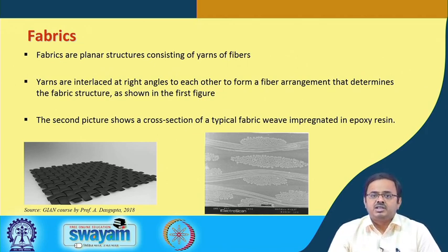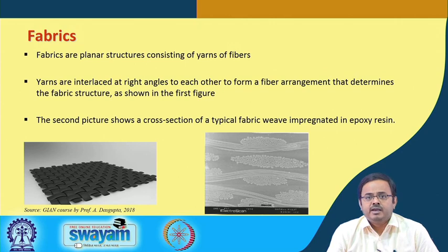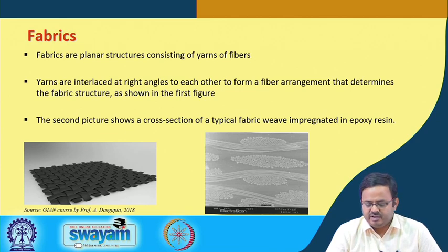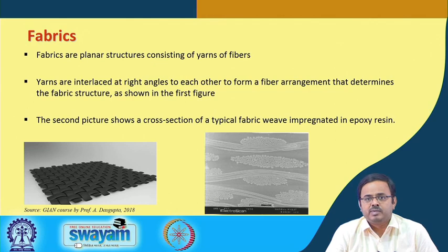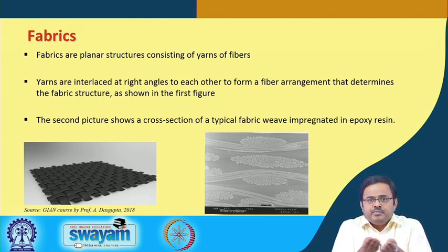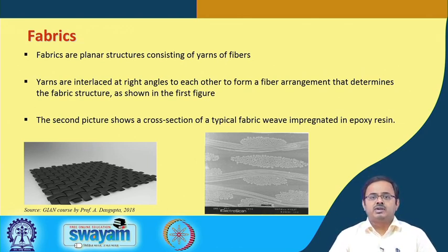And then what did we say? The laminate consists of this glass fiber in a polymer setting matrix. It is a binder. So, that you see on the right hand side. This is a typical fabric we have impregnated in epoxy resin. That is the polymer material. So, that gives me my basic motherboard structure or the circuit board structure. That green thing that you see is actually because of these. All right, we will come to that more.